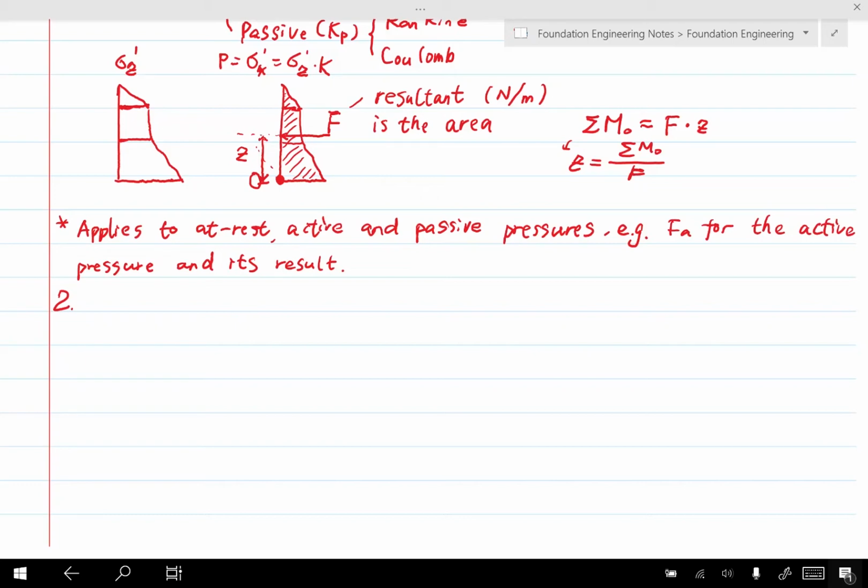For the retaining walls, what happens is that we will put backfill materials on the backside of the retaining wall. And those backfill materials, usually they are granular materials, have very good drainage properties, so that the pore water pressure will not build up behind the wall. That will hurt the stability of the earth retaining structures. And because of that, here the Rankine theory that we will be discussing is for the inclined granular backfill.